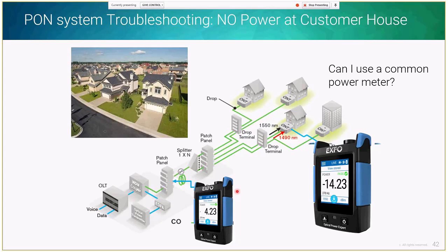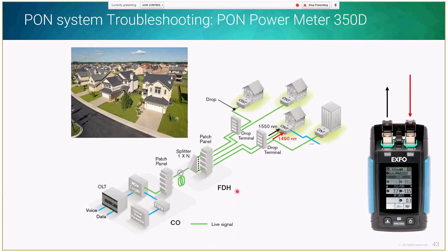So the question is, can I use a power meter for FTTH PON? Yes, you can use it, but you need to be very oriented, and you need to know exactly what you need to measure and in which situations it is going to work. So the other way of doing this is to use a proper PON power meter.